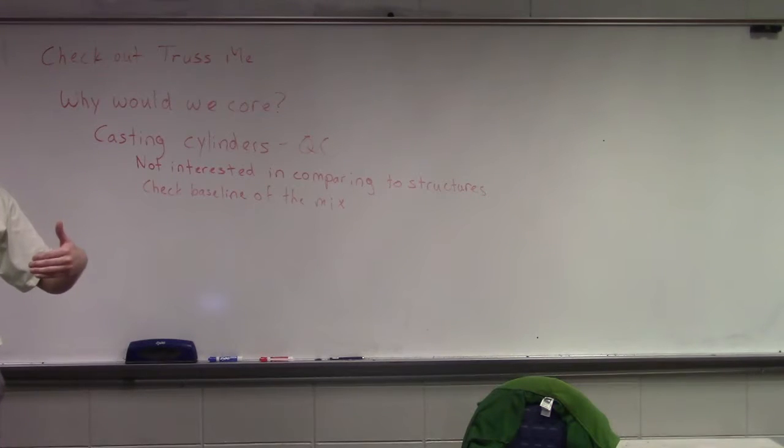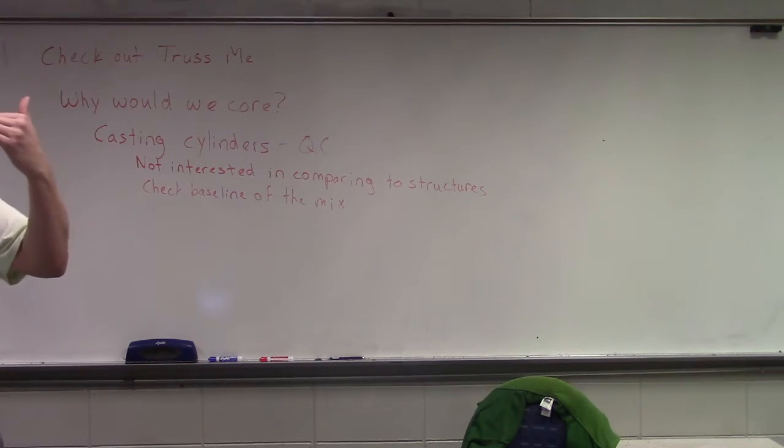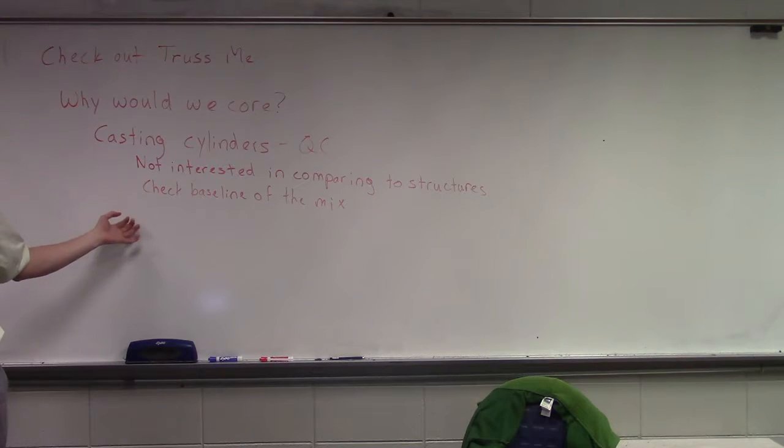If we have to go in core, all we have to do with coring is meet 85% of f'c with no core dropping below 75% of f'c, so our design strength. And the reason you have that allowance is, first of all, it's in the design, right? But second of all, we have to recognize that as we start cutting into that concrete with our core barrel, we're going to start fracturing some aggregate, we're going to start fracturing some of that hardened concrete matrix, so it's going to break at a lower strength, okay? So we also have to be careful when we're coring.